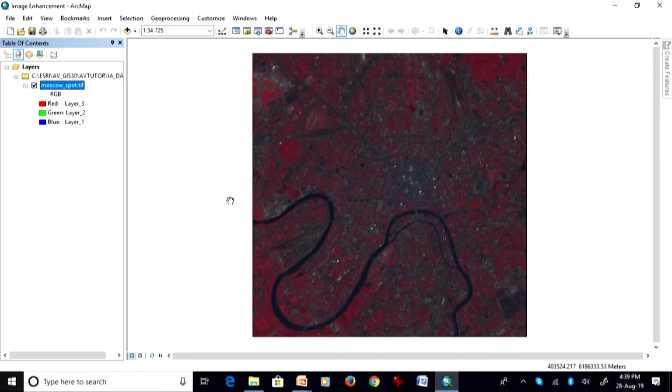In different software like ArcGIS or ADAS image processing software, you can save the entire project, and when you save the project, it occupies very small space. What the project does, basically, is store the path of different data layers which are present in the table of contents (TOC), and also LUTs and other processing one has done, and that will occupy only a few, maximum a megabyte of space on your hard disk, the project. And wherever your original files are, they will remain intact without any changes.